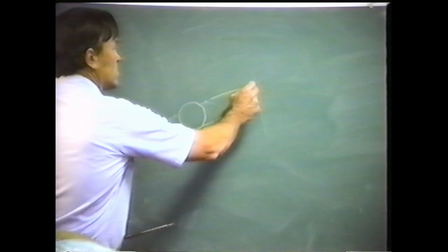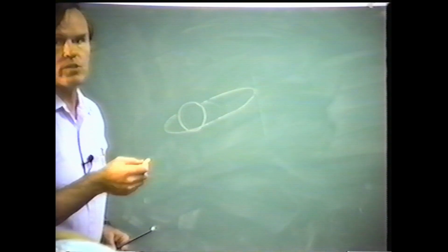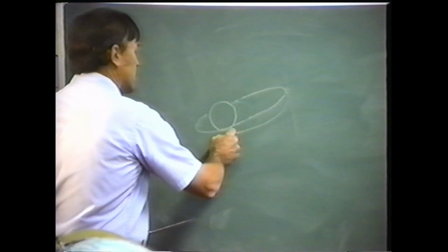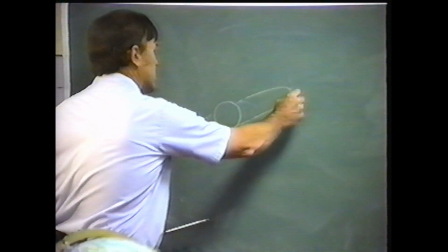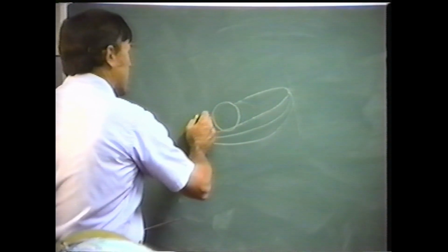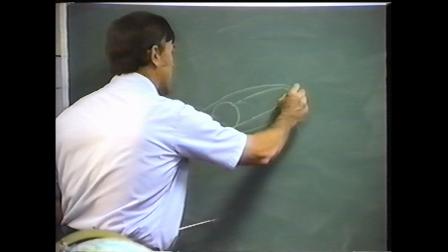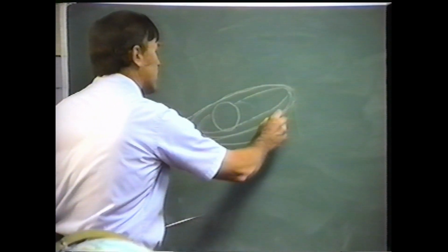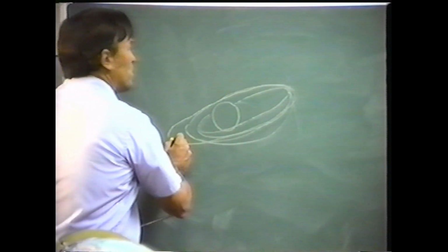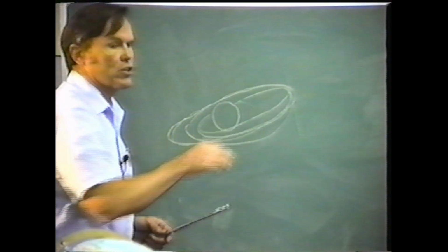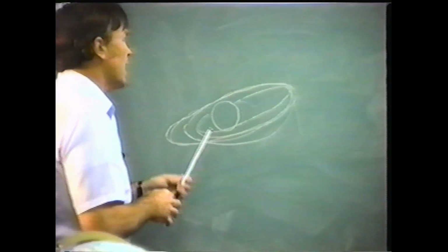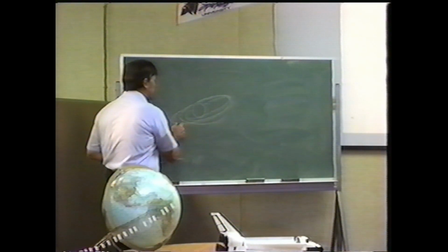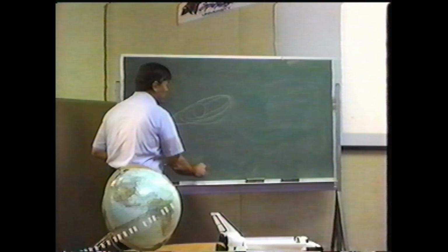And then as it gets to a certain point, the payload assist module fires again and broadens the elliptical orbit, and does this in stages, and just kind of stretches out the corners until in final eventuality, by timing the firings of these motors, it is actually put into the final circular orbit over the equator. And by timing these firings just right, the satellite can then find an eventual positioning over the equator.